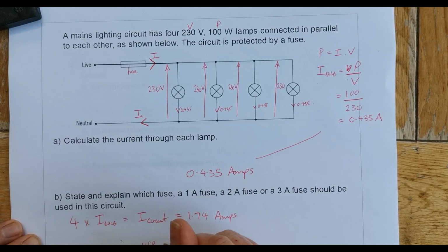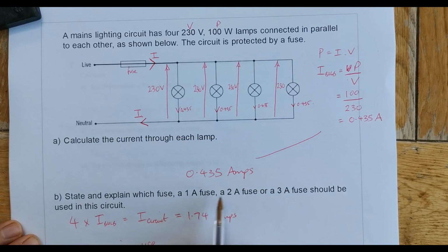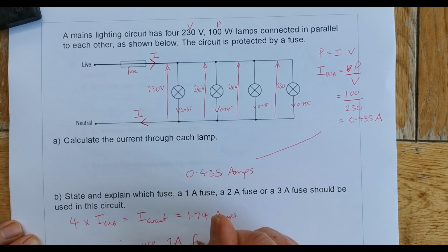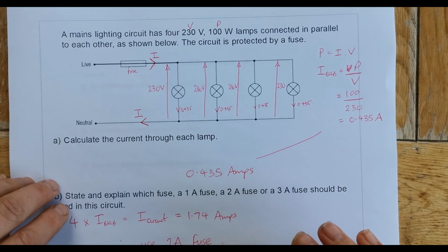Therefore, use the lowest possible fuse which would make it work, and that would be using a 2 amp fuse. That would be the best choice there. Let's have another look.